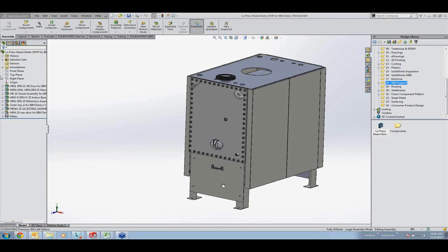There have been enhancements to sheet metal. So in 2014, we allowed the lofted bend to create actual bend geometry instead of approximations. There was a requirement that the sketch planes had to be parallel. Prepare this configuration with just the sketch profiles. So you can see that the two profiles are not parallel to each other at all.